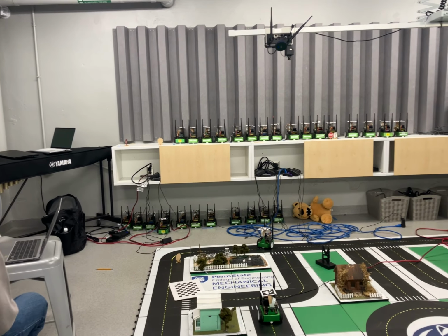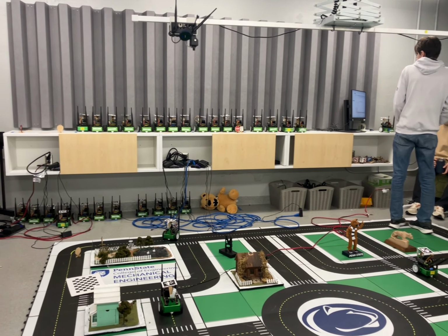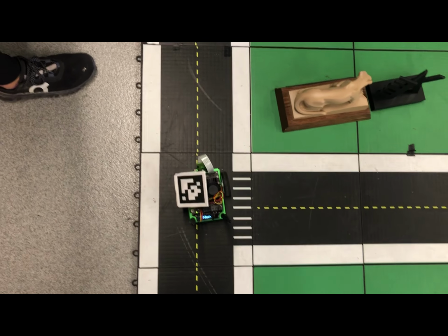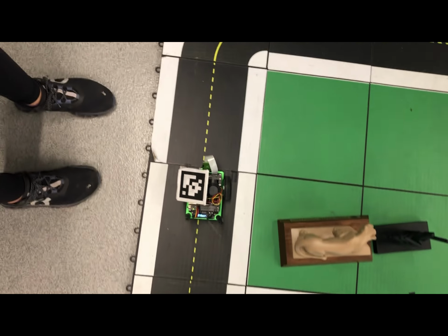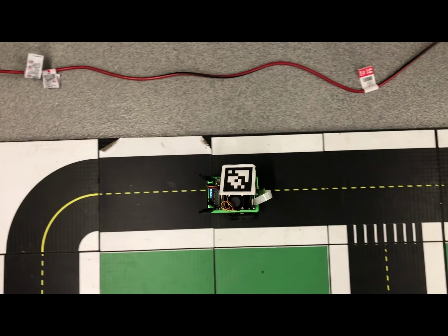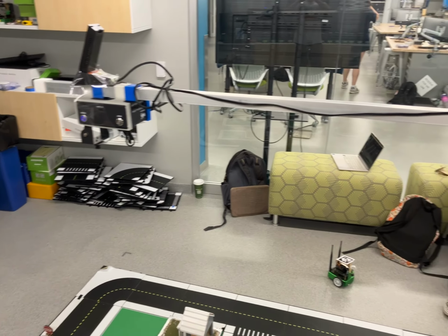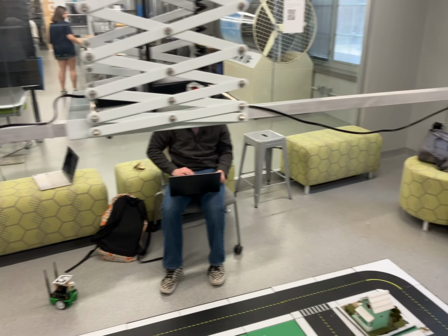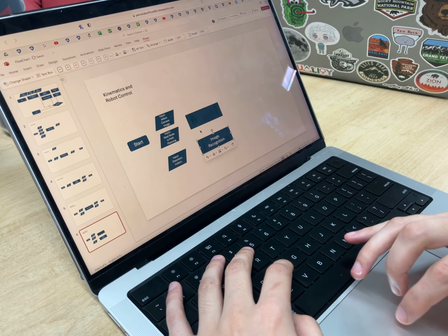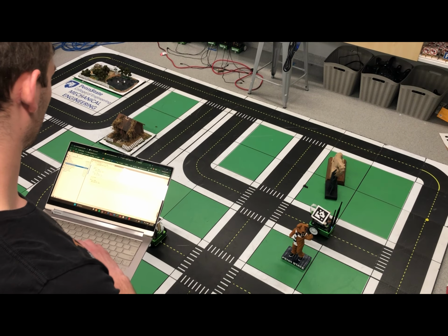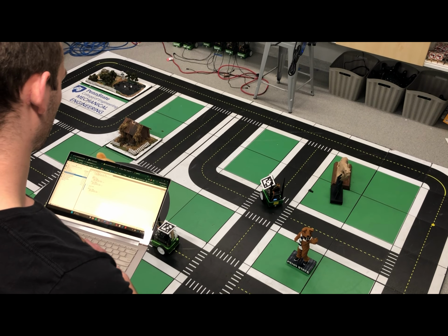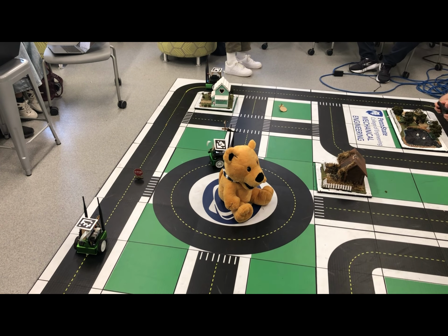In summary, our team added several functions to the JetBot that allow it to navigate autonomously. In the first lab, we tested kinematics and motor bias. Next, we explored image recognition and line following in the second lab. Finally, we created an algorithm for path planning in the third lab. To incorporate these capabilities into a single code, we created a comprehensive flowchart. This flowchart guided our team through the final project, where we developed a code that demonstrates understanding of kinematics, line following, and robot-to-robot communication with April tags.